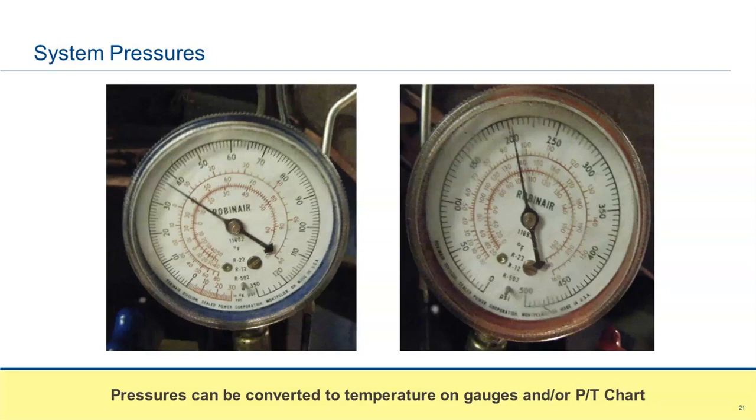We use the law of physics to read the temperature from our evaporator outside, okay? We can't take the door off the evaporator and stick our temperature probe inside to see what the temperature is. So again, we use the law of physics to take our pressures to get our temperatures, but it all starts out with a temperature. To prove that, if I start my sprinkler up outside, my pressures will change if I'm using my sprinkler around that compressor. But temperatures start everything, okay?